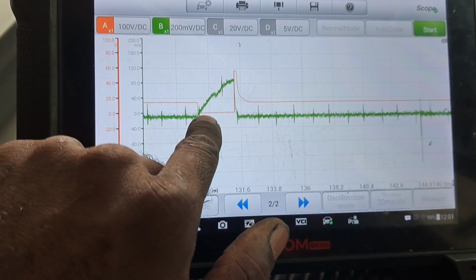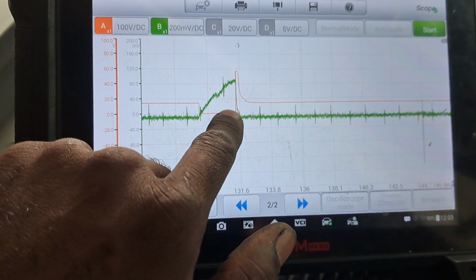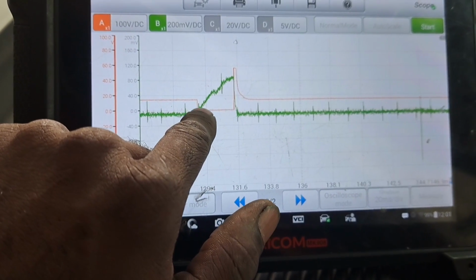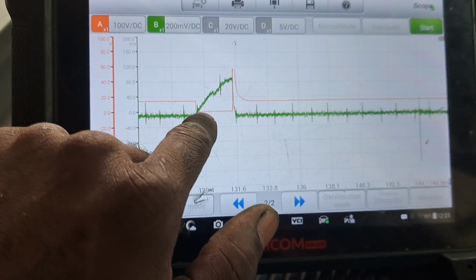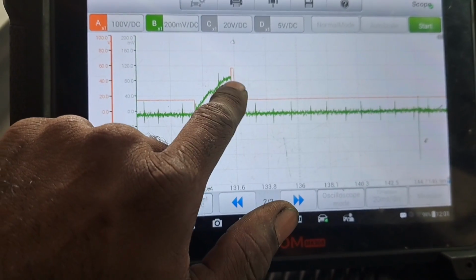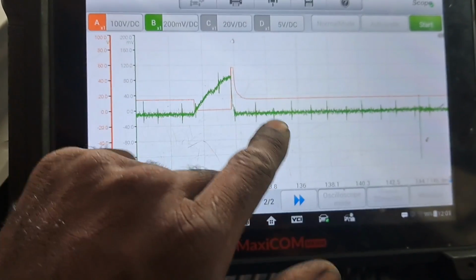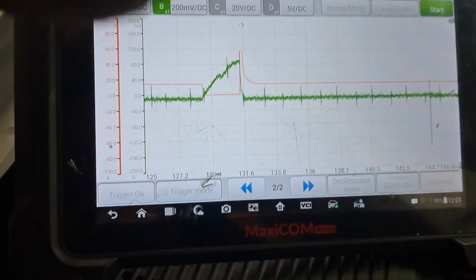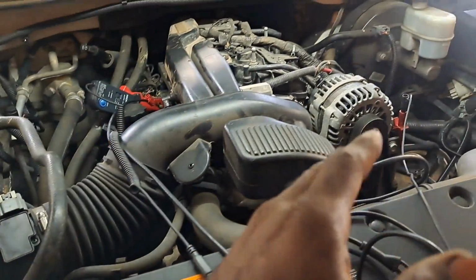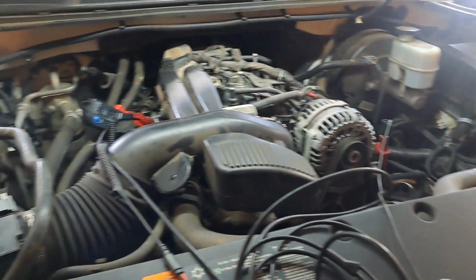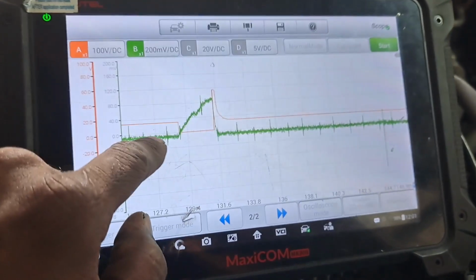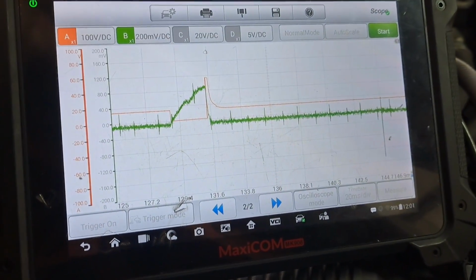So this is our peak hold down at this valley. That's the computer telling it to open and hold, and you can see how a current ramp builds, and when it releases you can see how it ramps and descends. So this is going to be the standard. I'm going to go to bank 1, do that same test on all of them, and see if any of them are outside the range of normality, since this is our standard and we don't have any issues on bank 2.